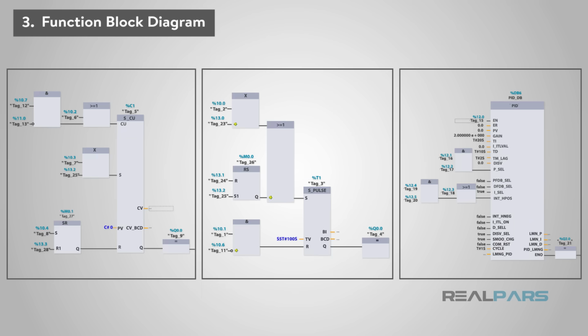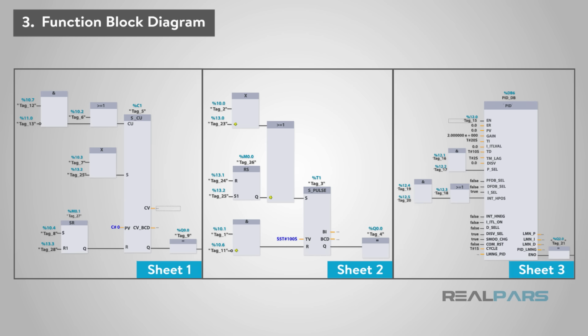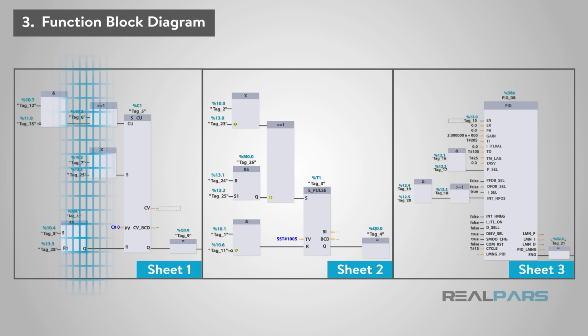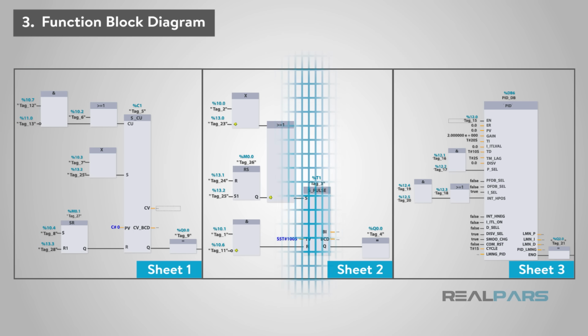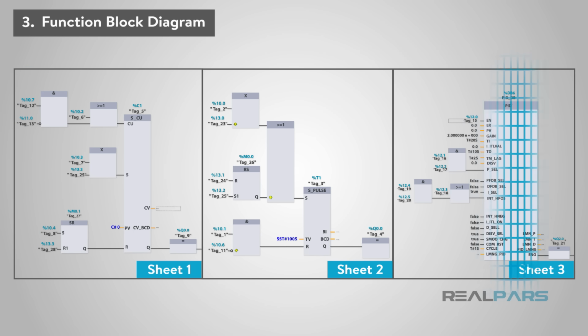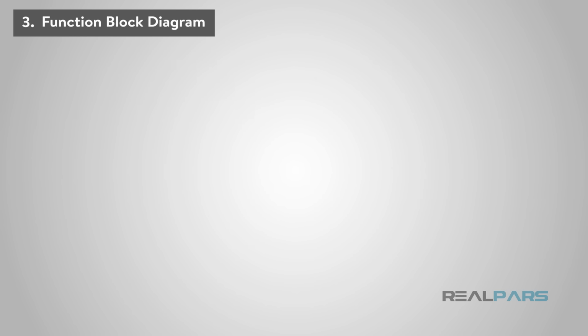Function blocks were originally developed to create a system that you could set up many of the common, repeatable tasks such as counters, timers, PID loops, etc. You program the blocks onto sheets, and then the PLC constantly scans the sheets in numerical order or is determined by connections which you program between the blocks.